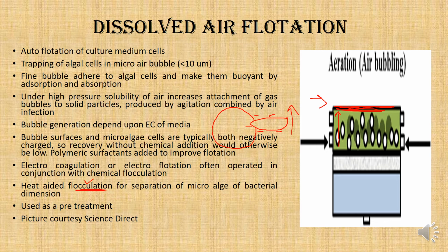The algae no longer attach to the bubble as single algae, but as algal flocs, and this helps in quicker removal of algae as a surface scum layer.